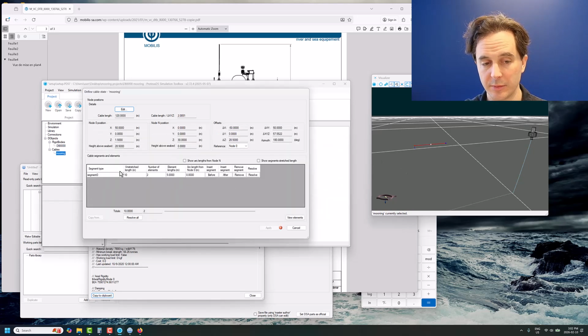Now you set the elements and the material properties for the elements. We've only added the 30 millimeter chain to this project so far from the parts library, so we'll use the 30 millimeter chain. It's giving a warning indicating that you have more geometry than you've allocated elements to it. The quickest way to resolve this is just to hit resolve.